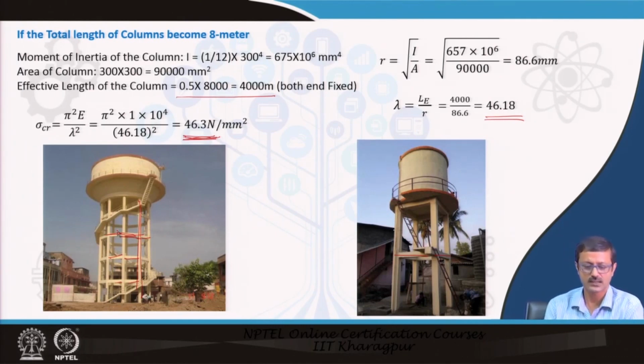So even though these beams look like they are not holding any kind of slab or ladder, nothing, just a ring connecting each column, it makes sense because it reduces the effective length of the column. Now you can calculate the effective length, maybe 2 meter or 3 meter, something like that, but here it is 12 meter, 15 meter. Definitely, with the huge amount of load of water, it is going to buckle, right.